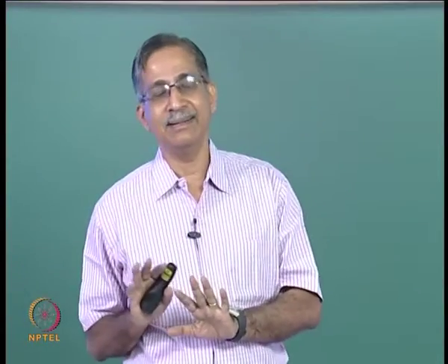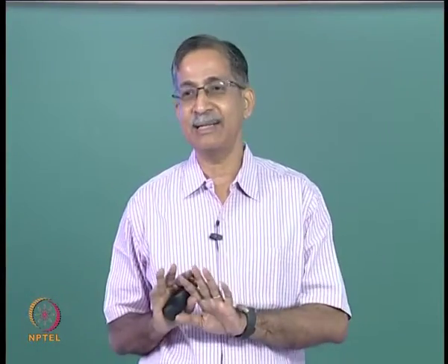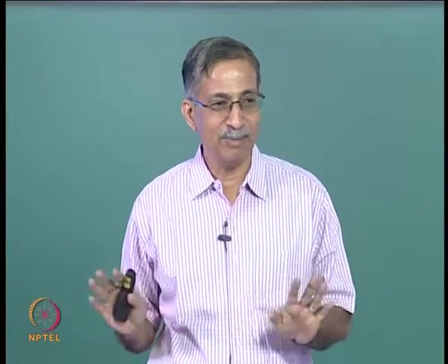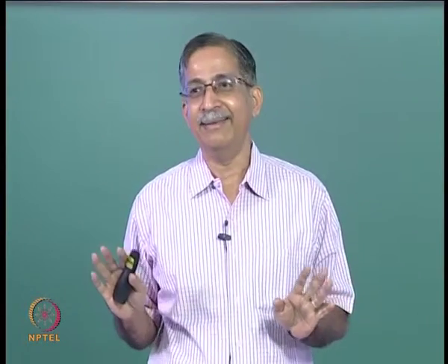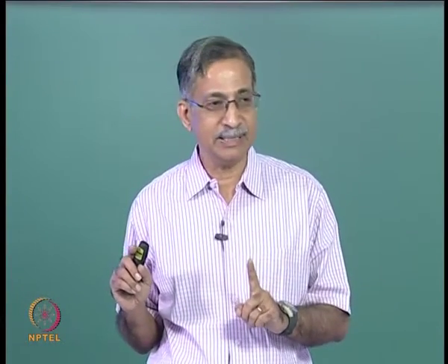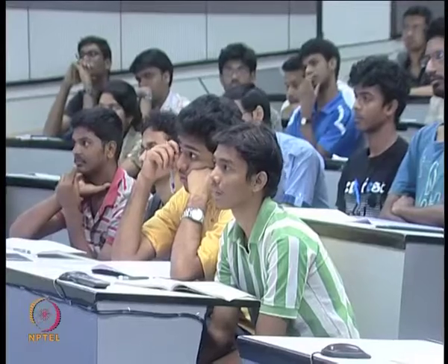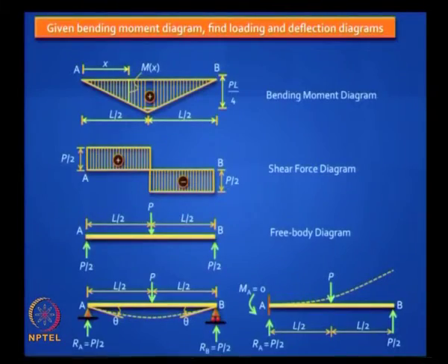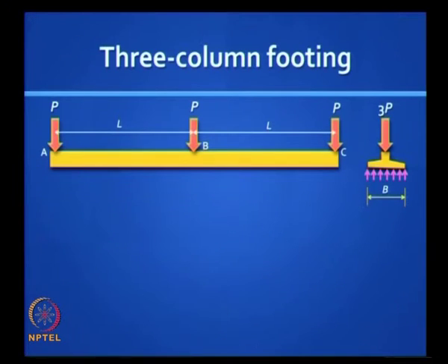You are dealing with a kinematic variable, so you must talk kinematic language, do not talk about bending moments and free bodies. They have the same curvatures at every point in that beam, the radius of curvature is exactly the same. So all you need to do is to have a rigid body rotation of one diagram, the curvature does not change but the deflections change, and that is what you do. You rotate this first diagram anti-clockwise by theta and you will get the other diagram. So it is very important to understand these relationships. So that is 2 theta at the free end of the cantilever.